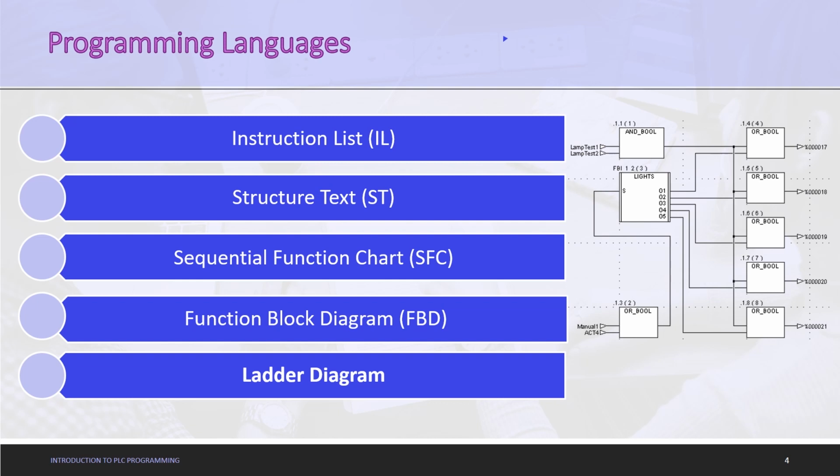In the case of a function block diagram, we can see that there is a block which is used for the logical operation, and this block has the code of logical operation AND inside it. What we need to do is assign 2 inputs to the block. The output will naturally be the logical AND operation of the 2 inputs. So this block can be used again and again in the program without having to write the same code. We can just copy and paste the block.